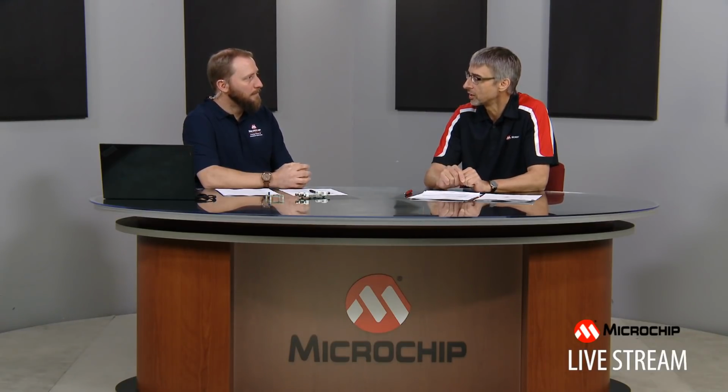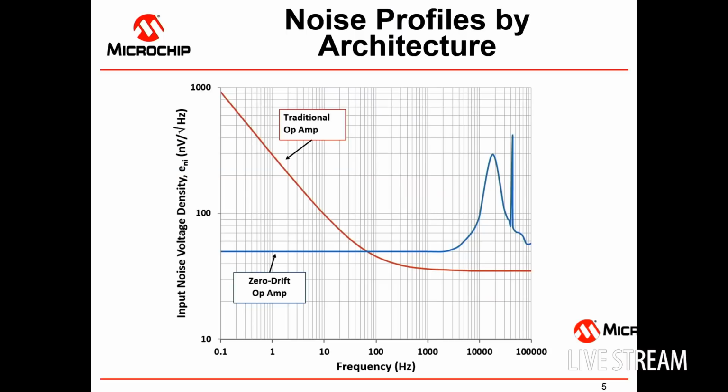Now, the downside is, as mentioned, as part of the noise shaping effect, we have the hump that has moved to the right here, to the higher frequencies. Now, there are a couple of things going on. If you recall, on the architecture, we have the main amplifier and we have the correction path amplifier. At one point at the end, those two signal paths have to be merged back together, and they have to be compensated internally, individually, to assure stability. And that causes this hump effect that you see, which is around roughly 20 kilohertz or so in this particular case.